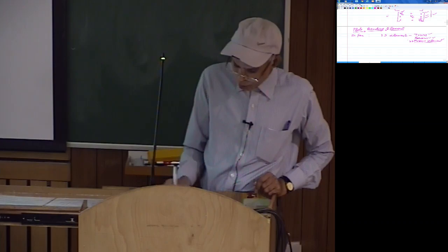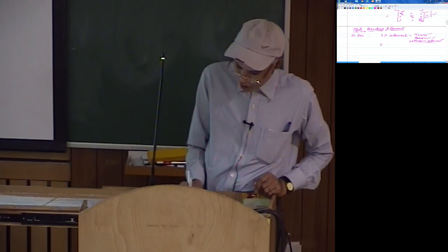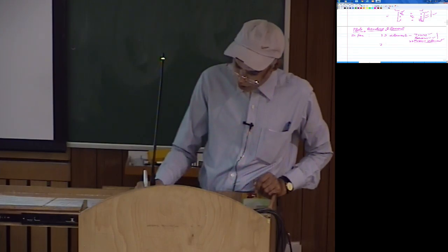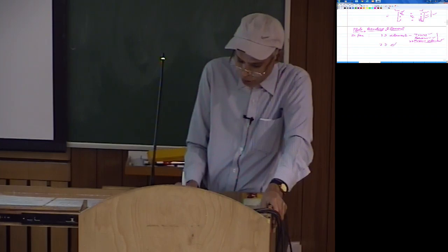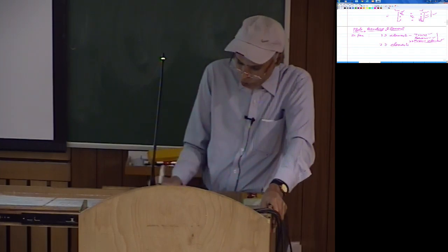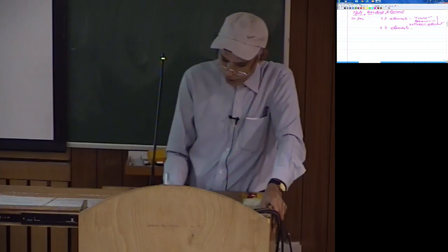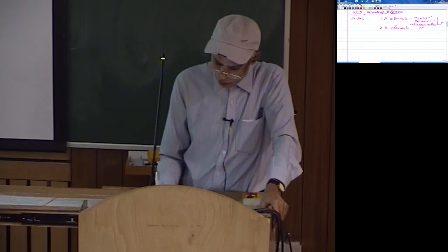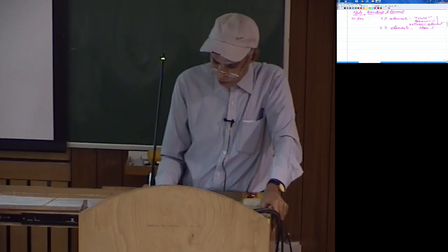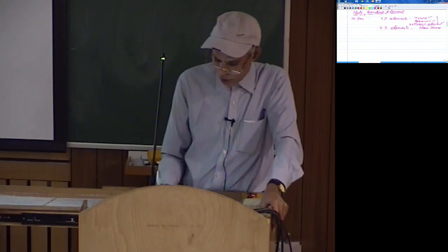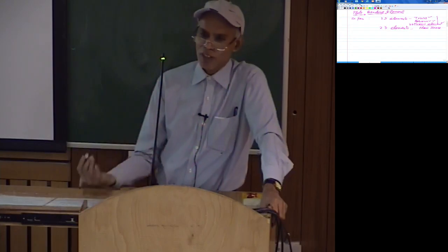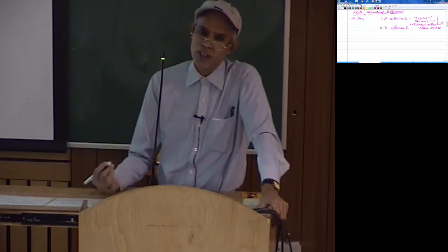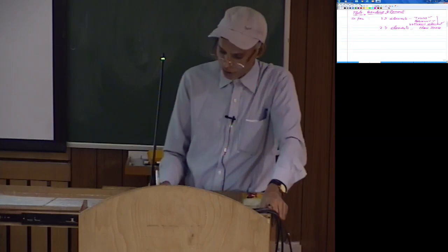So many other problems can be covered under this, and as long as whatever assumptions we have made in these are satisfied, you can actually model those structures using these elements. Then we discussed 2D elements, and in 2D what we discussed was plane stress, of course isoparametric formulation in physical coordinate space, 4-noded, 8-noded, so on, various categories under that.